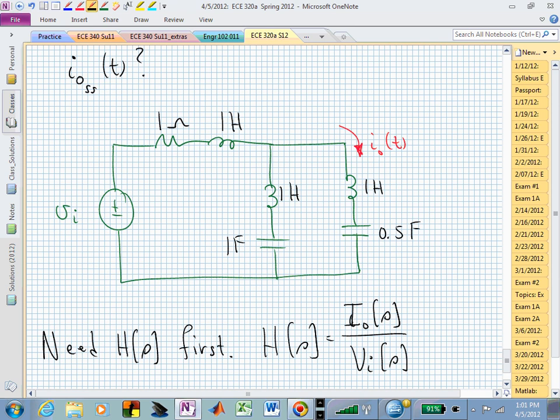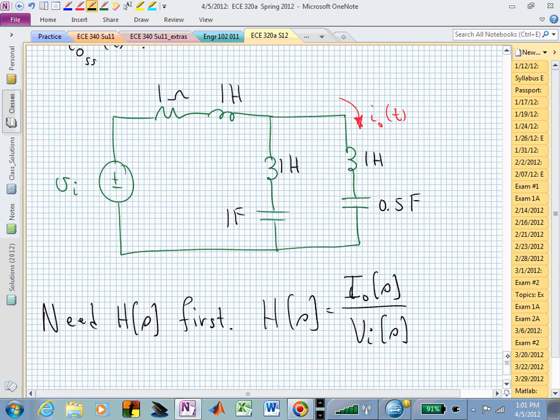It actually makes for a slightly easier problem if we do a source transformation on this piece. Meaning if we find the Norton equivalent of that, now everything will be in parallel, and we can now find the rightmost current in that parallel configuration. Is that making sense? You can solve this however you want. You could do a KCL equation right now at the top if you wanted, and it won't be that much different.